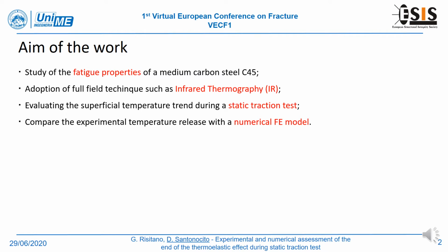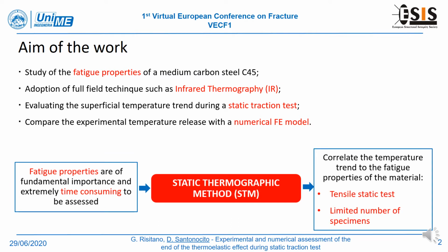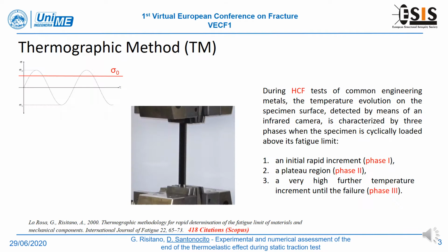The mechanical properties of the material were evaluated and the temperature trend of the specimen surface was monitored during tensile tests. The experimental temperature trend is compared with a numerical finite element model to assess the end of the thermoelastic effect. In this work, the static thermographic method is proposed as a rapid test procedure able to correlate the temperature trend to the fatigue properties of the material during a static tensile test, adopting a very limited number of specimens.